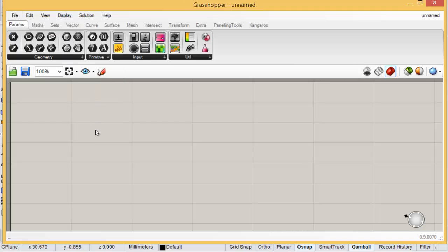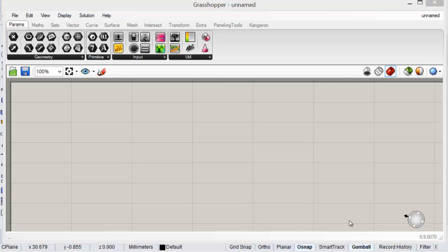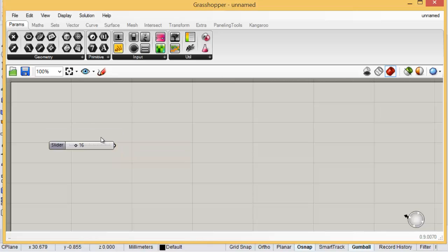The same elements we used in Rhino we're going to use in this. We're going to be using a circle, an offset amount, an extrusion amount. Apologies, helping young Tracy there. So we've got the same parameters as in Rhino. We have an initial finger size, so I'm going to double click here and put in a number to let it know we'll be working with a number in this slider. I'm going to put in 16mm, because that's around about size N or something. So we've got a slider over here that we can now change.